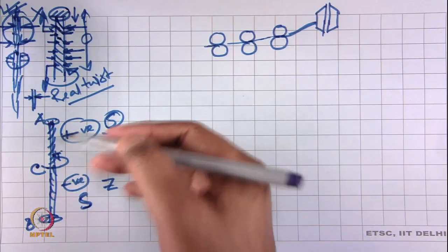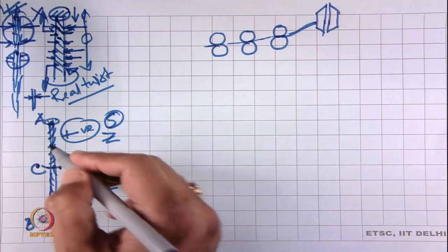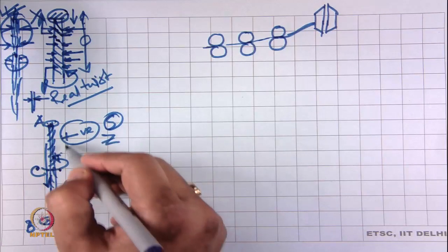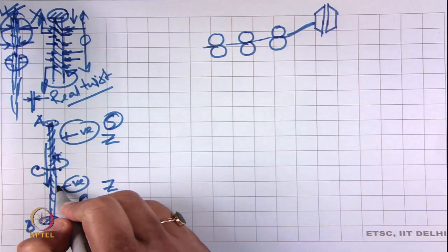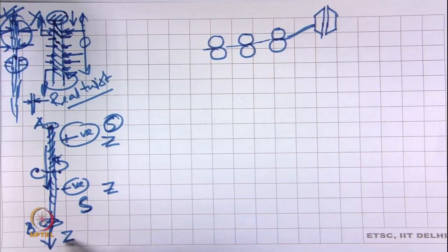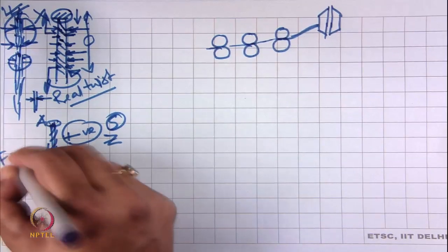So, this is actually not real twist, because when the yarn moves, this will get automatically cancelled out and finally the yarn will be 0 twisted, and this is called false twist.